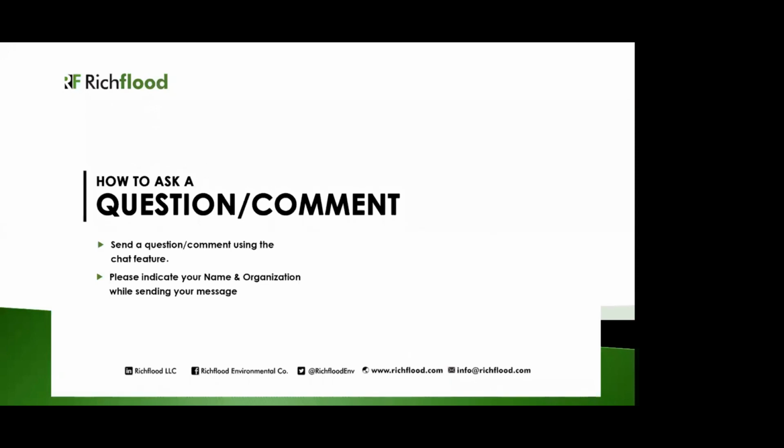The second question asked about the required information in a site investigation. I started with that when I shed light firstly on the terminology of our topic of today. So I'm just going to go over it again. Now, the site investigation has to do with collecting information and assessment of data. It involves collation of desktop information, appraisal of data, assessment of the ground conditions, and provision of an interpretative report.